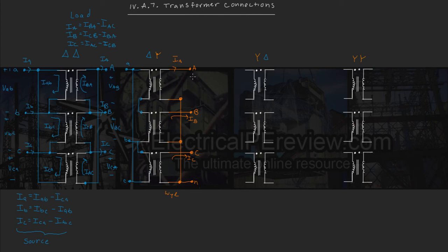So we're going to have our A line voltage, or plus V.A.B. minus, our B line voltage, or plus V.B.A. minus, our C line voltage would be plus V.C.A. minus. And then all of our phase voltages, we're just going to draw C because we're low on space, would be starting with the polarity at the node it's coming from, so VC, and then negative at N, the neutral.